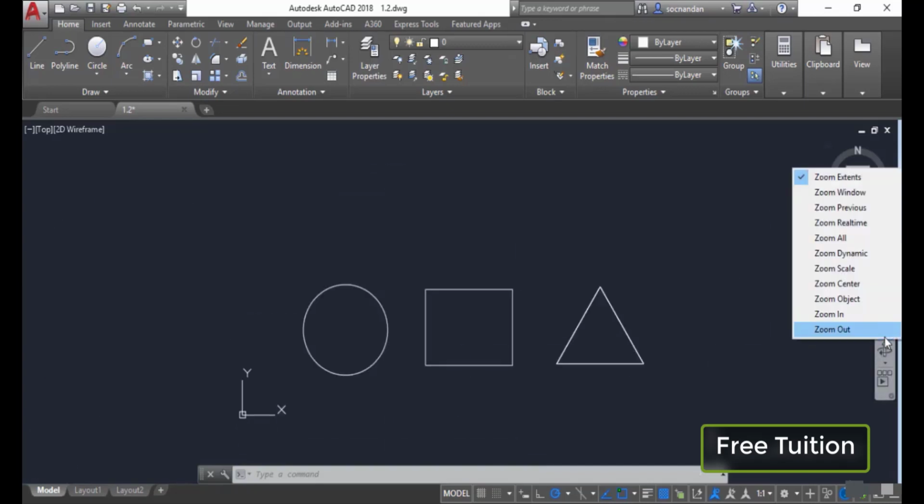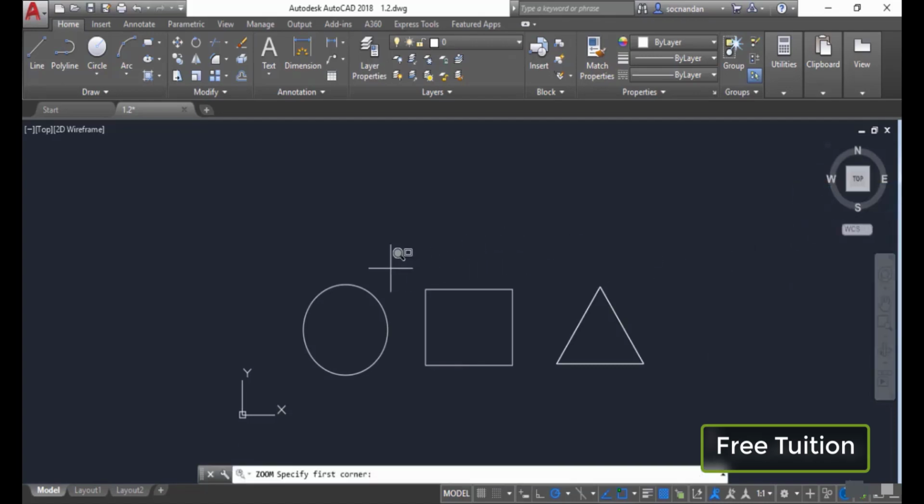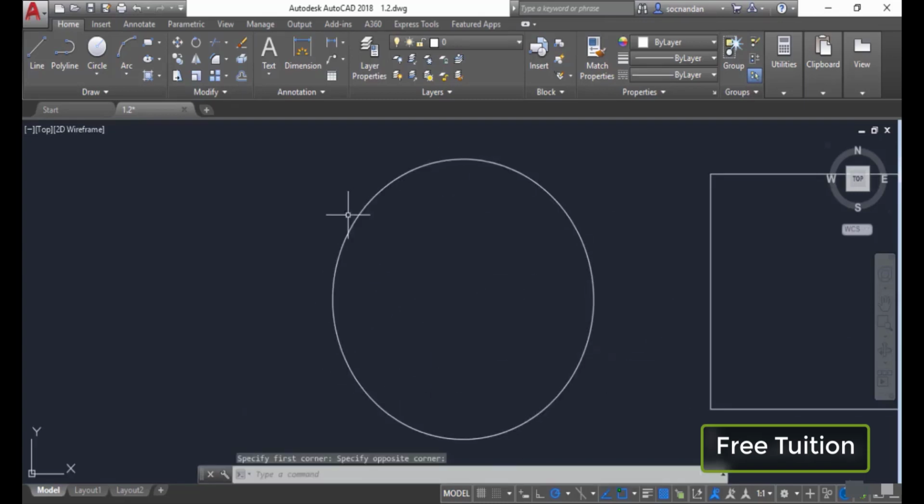We also have some other options like this zoom window, which can be used for zooming on a particular object. For example, let's say that we want to zoom into this circle. Simply make a window around the circle, and the circle will be brought into perspective. It will be zoomed in the current workspace.